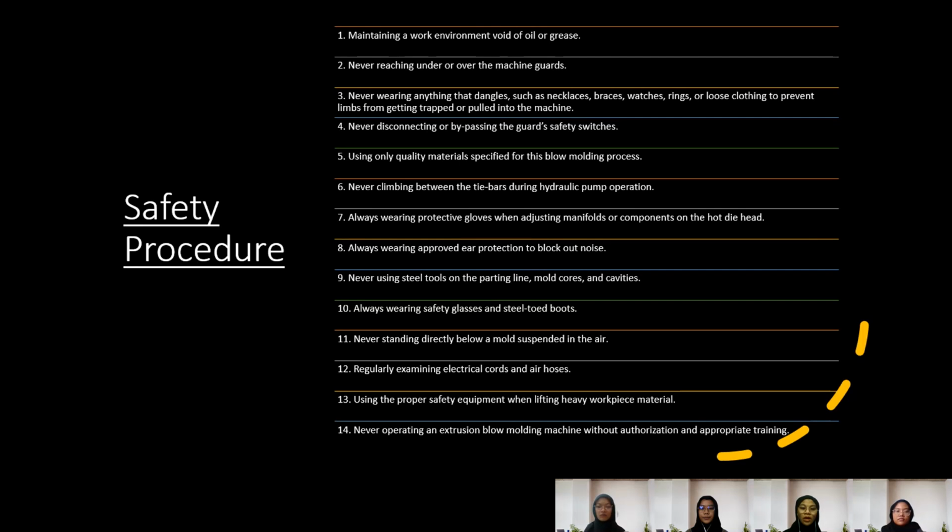Number 4, never disconnecting or bypassing the guard safety switches. Number 5, we must use only quality materials specified for this blow molding process. And number 6, never climbing between the tie bars during hydraulic pump operation.